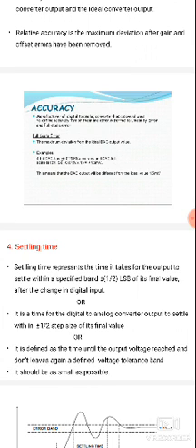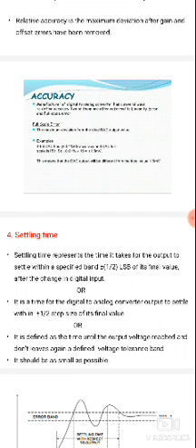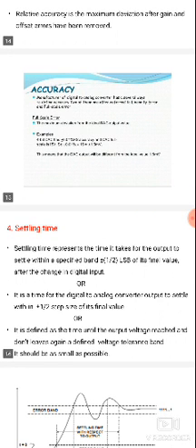The main two terms are linearity error and full scale error. If we are getting a noisy output, the noise is in terms of either linearity or full scale error. Full scale error is the maximum deviation from the ideal digital to analog converter output value. Next, for example, a 4-bit DAC has plus or minus 0.01% of full scale accuracy.